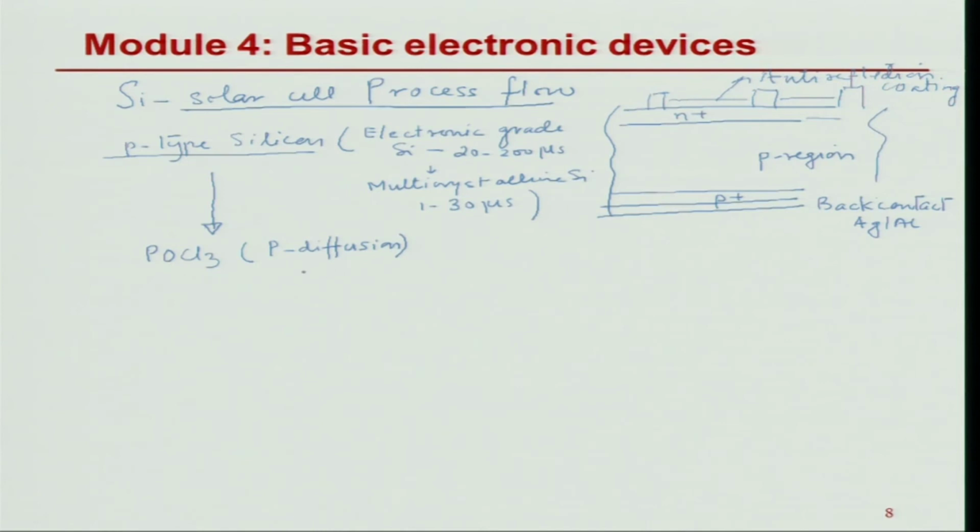As it comes to the surface of the silicon, POCl3 oxidizes, as one brings in the oxygen along with it, and it changes into P2O5, which reacts with the silicon and gives phosphorus plus SiO2. And this phosphorus is then doping the original p-type silicon to whatever level is desired.